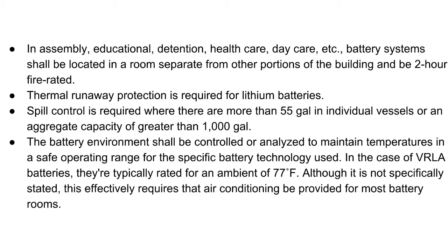Lead acid will generally give you an operating range where the batteries can be all the way down to freezing temperatures, even below freezing. They can get hot too. They can be in 90-degree weather. So unlike, say, a lithium-ion battery, where the manufacturer may say you have to keep it out of the sun, you have a little bit more operating range with lead acid.